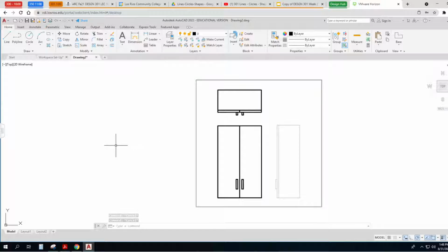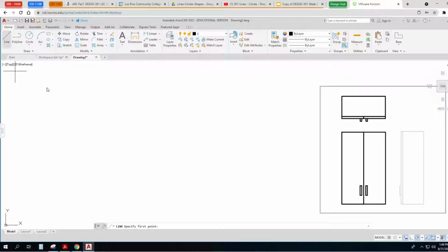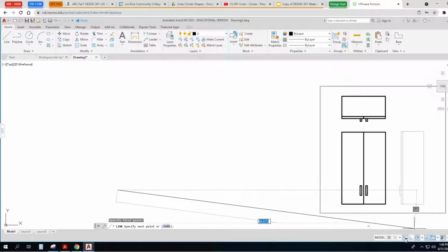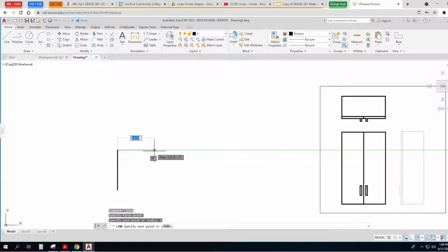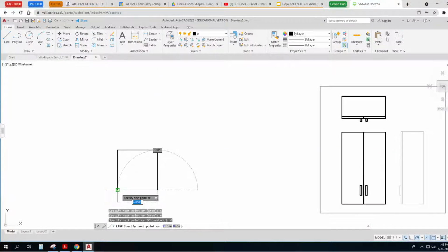Okay, so here's the way to do it. So on that particular one, see how since I have my dynamic on, and now I'm going up in the Y direction, I can type 6, enter, and I move my thing over, 6, enter, 6 down, and 6 over.